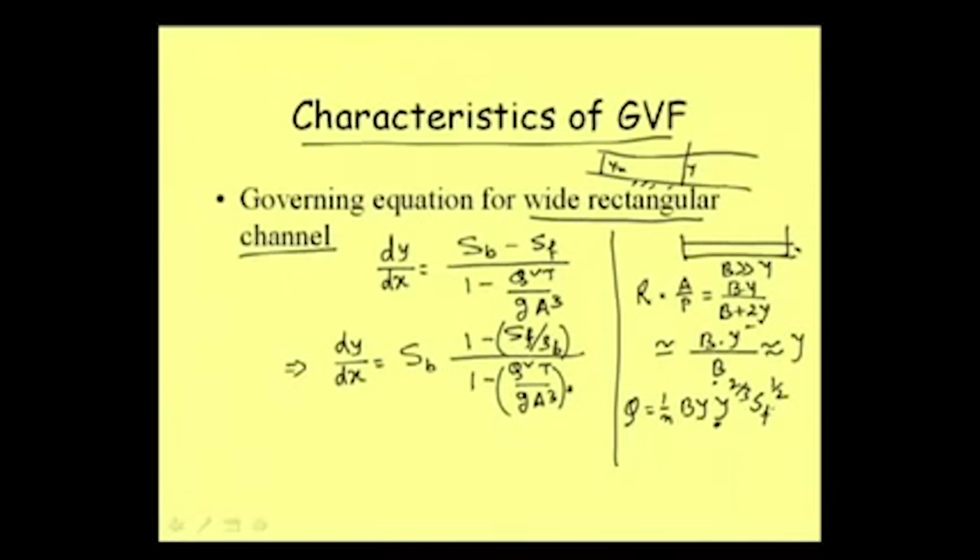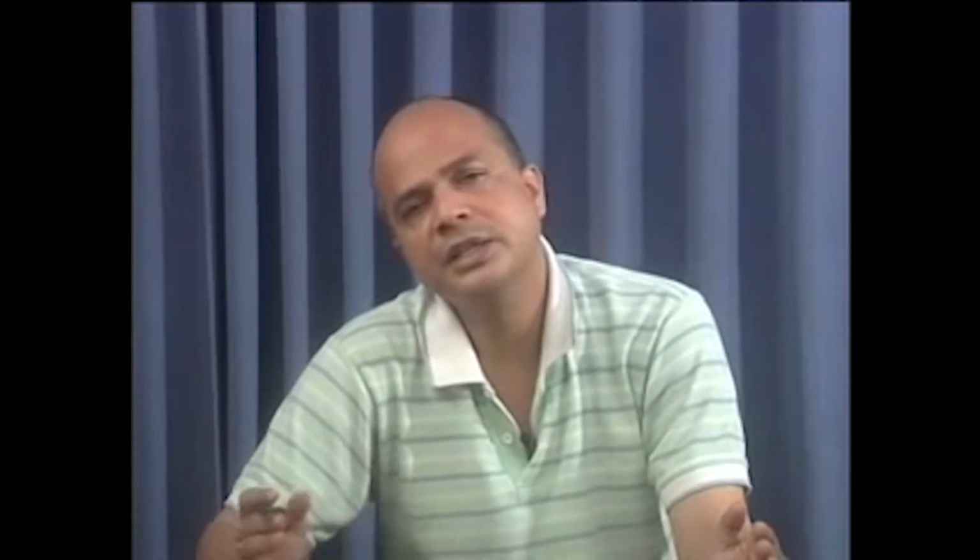And if we remember, when we did a derivation for this resistance flow formula, basically this S value is coming as SF. It is the friction slope. That is, we are basically interested in finding the slope of the hydraulic head line, that is the total energy at one point upstream and total energy at the downstream point.